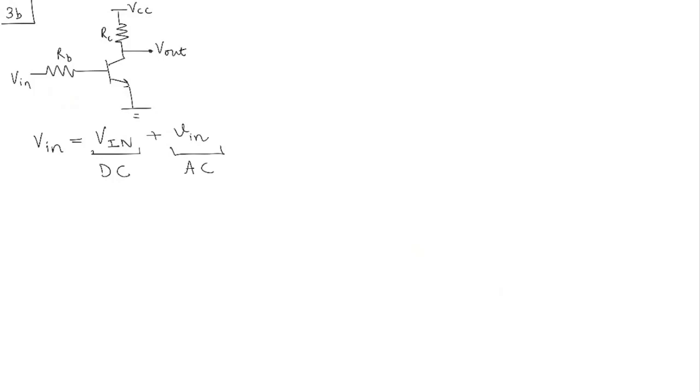Of course, the answer to that question is that we want the transistor to be working in active mode, and the limits are going to come from there. So, what was the output that we calculated in the previous slide? What we did was we said V out is equal to VCC plus beta RC divided by RB times 0.7 minus beta RC divided by RB times Vn.